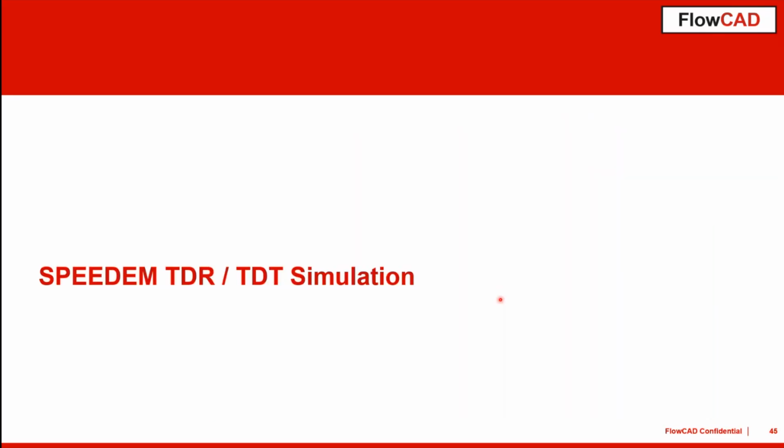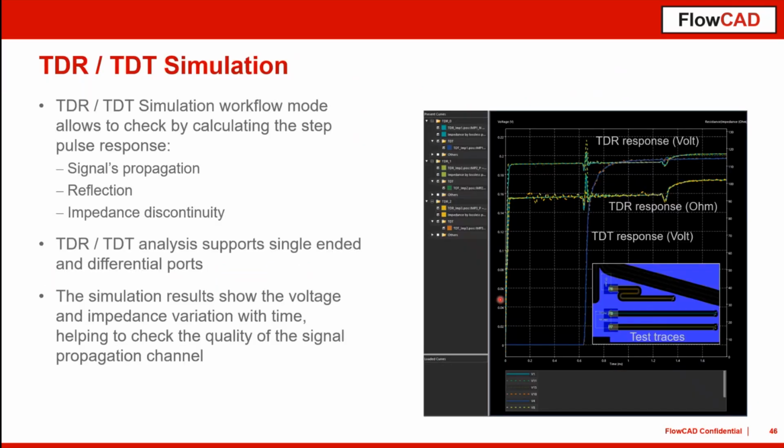And finally, that's also a very nice way to quickly check your design if specific impedances meet your requirements, and if there are any disturbances or impedance mismatches in your traces. In this case, this sample shows some impedance measurement traces on a PCB, and here we have the layer transition from top to bottom.